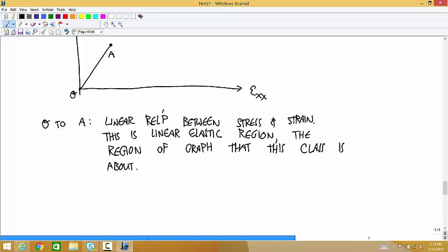So it's a line because of the linear relationship between stress and strain. Since this is still an elastic region, that means that if you let go, if one of those clamps slipped off or if you stopped loading it, no matter where you are along this line, that sample will return basically instantly back to its original shape. Okay? And we're talking about very small strains, you know, like 1 times 10 to the minus 4 or something.